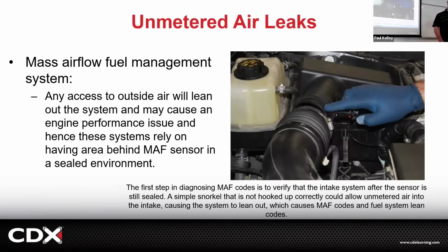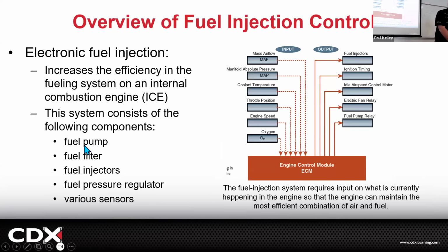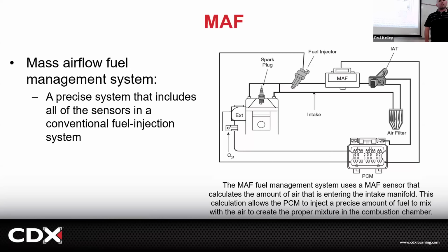Whereas if we had an issue such as a leak in the tube or low fuel pressure or whatever, it might not be picked up by the MAF, and it might not spray the right amount of fuel. That might be because of a tear in the hose, or because of a bad fuel pump, or because of a bad mass airflow sensor, right? So things are going to get kind of complex when we start to troubleshoot the actual fuel injection system that has to do with the air fuel ratio being correct, okay? So that's where we're going